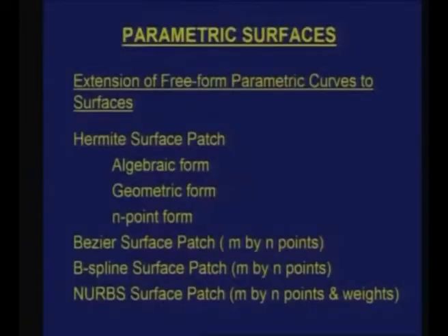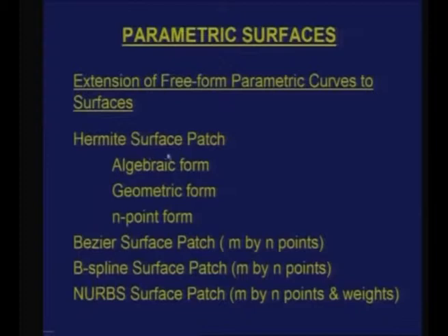So, first, we can extend free form parametric curves, which we discussed earlier. The same definitions can be extended to surfaces also. If you recall, we discussed parametric cubic curve or Hermite curve, Bezier, B-spline and NURBS curve. So, in a similar fashion we can extend the definitions to surfaces. What we will see is we will look at a Hermite surface patch. As I said, the word patch here basically refers to a surface with fixed boundaries, and